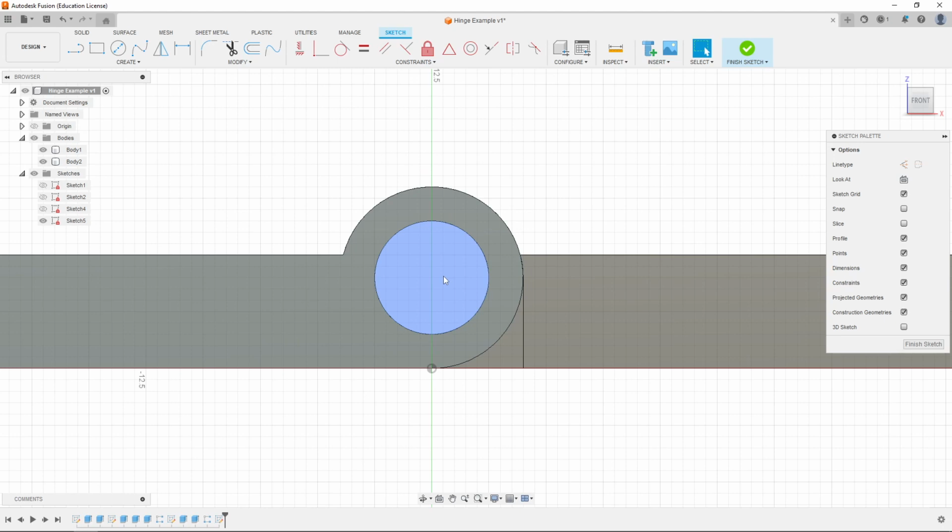For us, in my experience, about 1/10 of a millimeter in difference, or maybe 15/100ths of a millimeter, is enough to give us grip so that they hold on to each other, but they're not too snug where we can't slide it through. So I'll do about 1/10, and I think that'll be good.